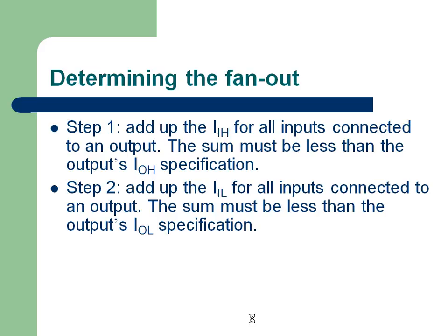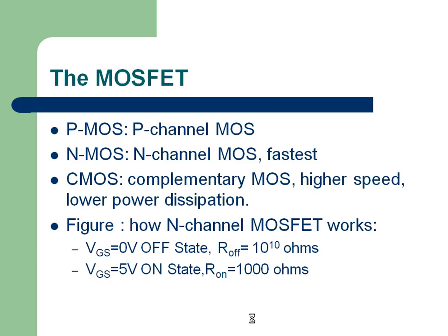Determining the fan-out we discussed yesterday. When the output is high, that is IOH, that is one constraint. Output low is another constraint. Whichever becomes the more dominant problem, you have to take that. Let's say the output-high case decides fan-out to be 6 and the output-low case decides fan-out to be 3; you take 3. That's all.